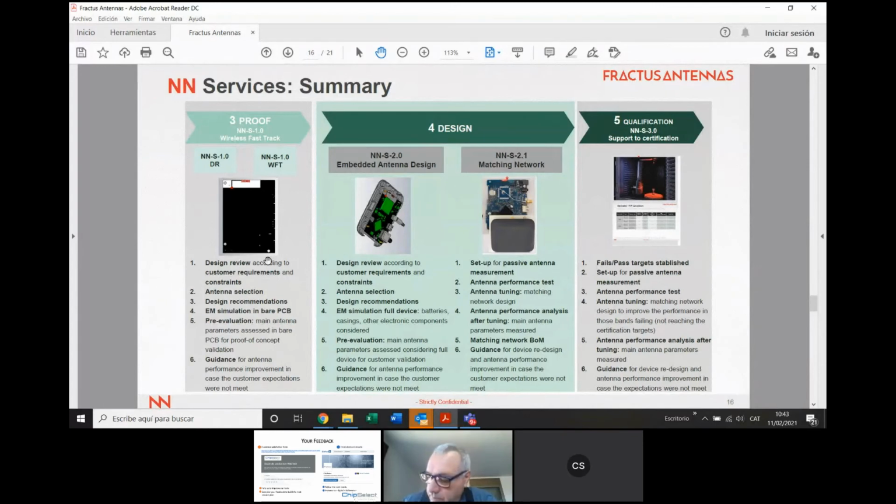Afed is asking the question, matching circuit could resolve the S11, but what about the other performance like efficiencies? When we make the matching network exercise, always in a passive mode, we are always giving the customer a report where we are minimizing the VSWR with the S11 parameter, as he mentioned. But remember that we are making the exercise in two vectors. One vector is the S11, and the other vector is the efficiency.